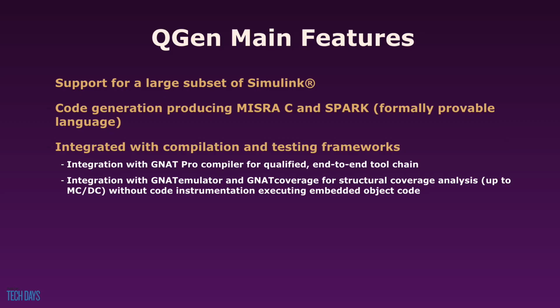It is integrated. We have integration at various levels between QGen and the compiler. You can do an end-to-end tool chain. So from one vendor, you can get your model code generator, your compiler, your debugger, your cross-target debugging, and so on. Integration with GNAT emulator, so that if you want to emulate a target on the host, you can do more efficient testing and so on.